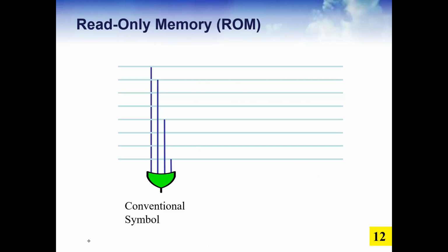We have seen that using a decoder circuit, we can design any function, provided you know the minterms. For example, if you have a 3 to 8 line decoder, we have 8 outputs, and any particular output will be high. We have seen how a decoder can be used to implement a function if we know the minterms. So this is the conventional approach.